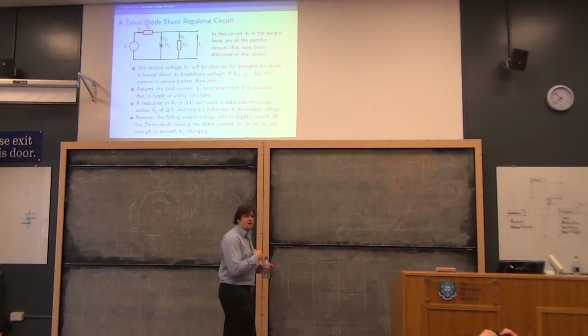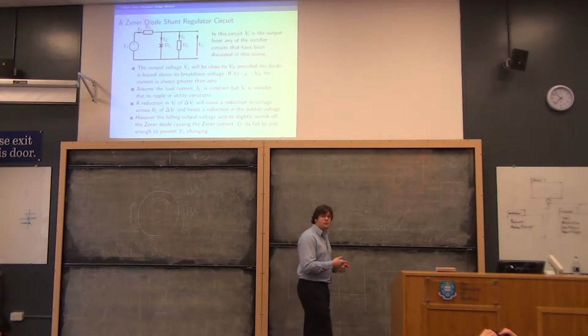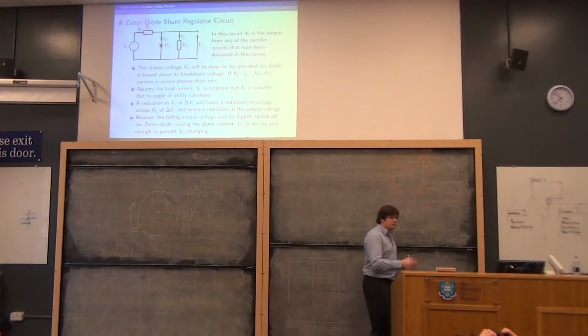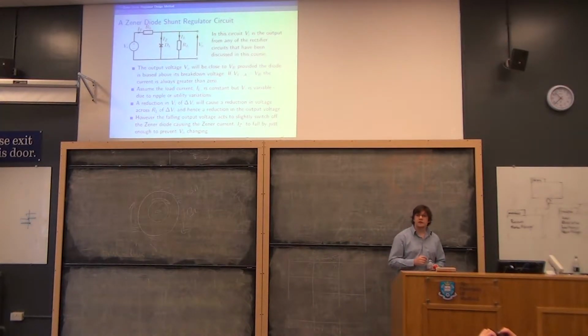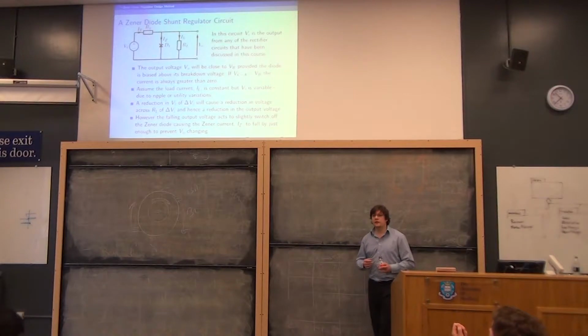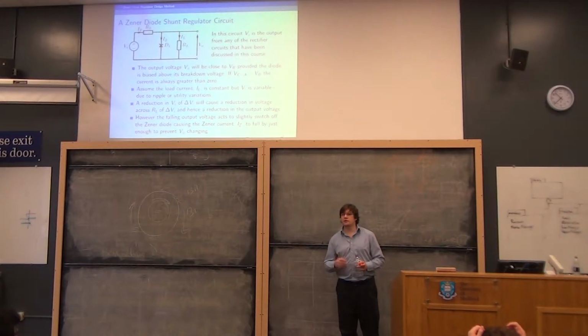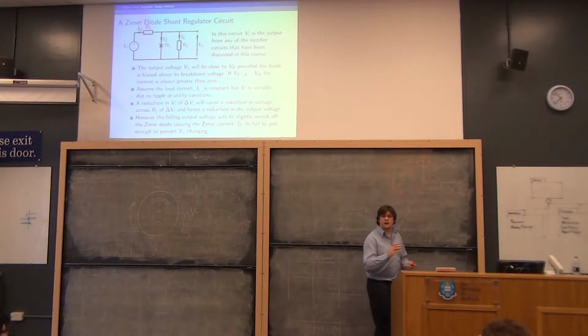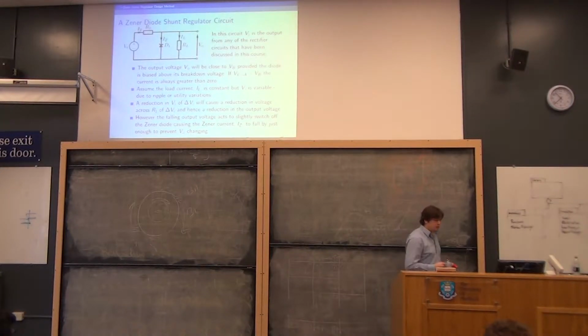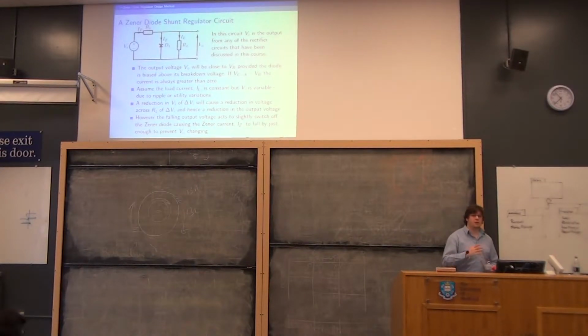And I've just said that VI is considerably larger than the breakdown voltage of the Zener diode. So as soon as we put this voltage on, as soon as we switch on VI, the Zener diode should break down, because the conditions that arise as we turn it on are such that it ought to. That's to say the ratio of R1 and RL is just about right.